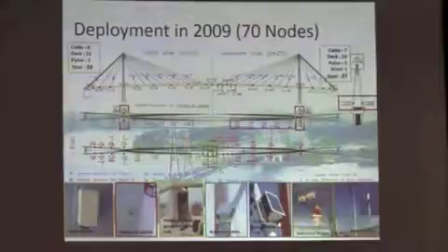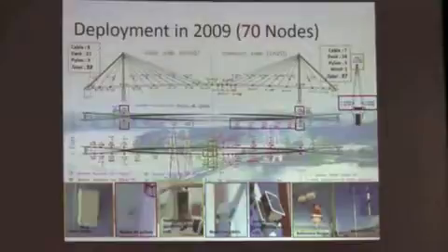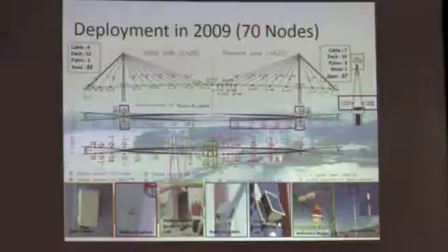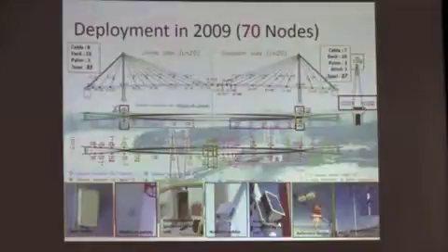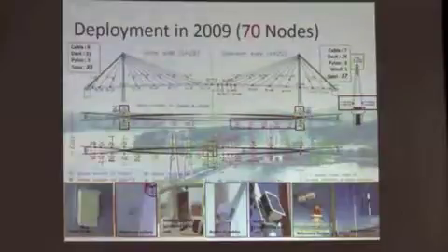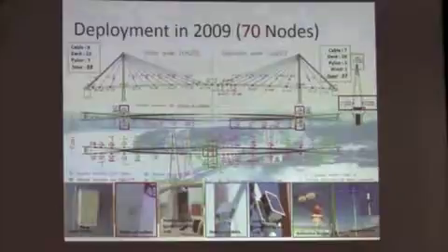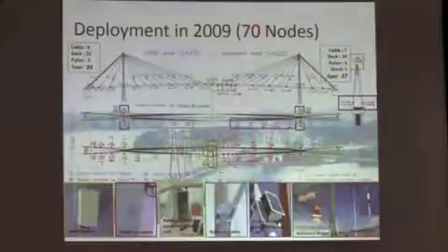They had like 128 accelerometers. So we had 640, but it was the number of nodes, that is how many wireless computers you have. They had 64 nodes, and they had 2 accelerometers and 1 temperature sensor. In each of our nodes we had 3 accelerometers, and we had a temperature, humidity, and light sensor. I don't know about better, but there's always a friendly competition between the 2 civil engineering programs. This shows you how some of the nodes were deployed.